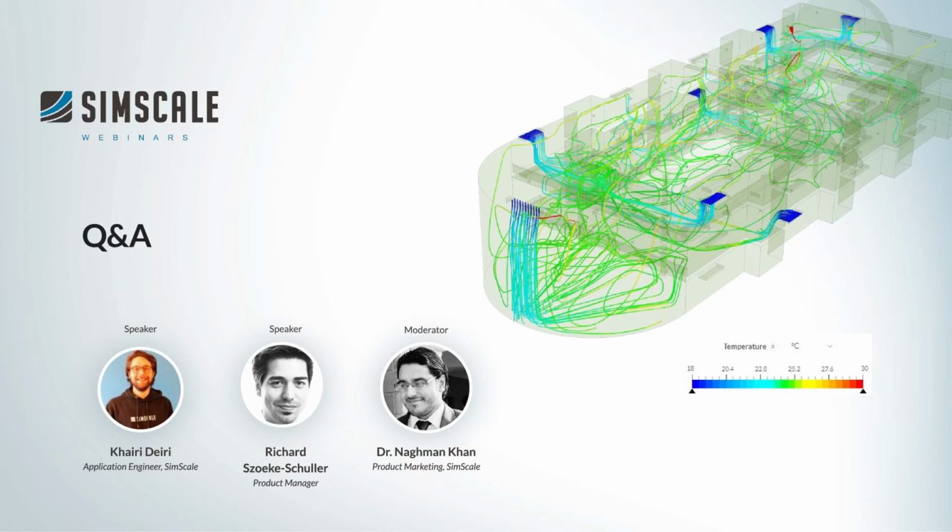Regarding meshing, we have a focus on automating as much as possible and having the least required user interaction, but still giving the user the flexibility that they need in certain corner cases to really go into much detail and refine locally as they like. So we have more or less smart mechanisms to define local refinements, local cell sizes based on the simulation setup. We first do the simulation setup on a CAD model, and based on the information from that, our meshing algorithm takes this into account.